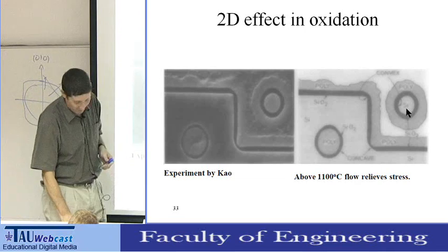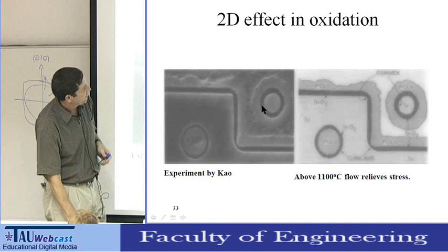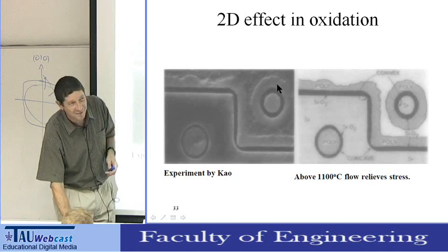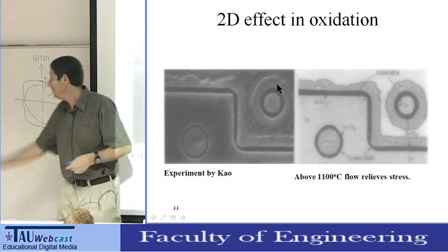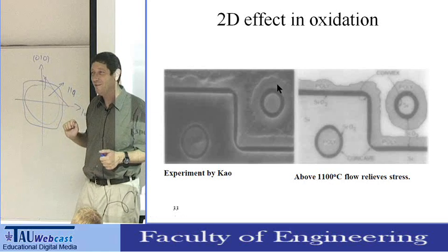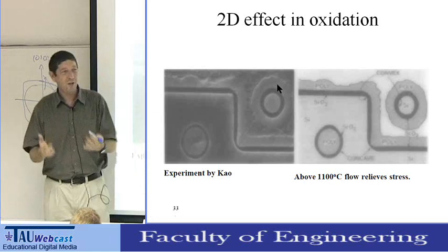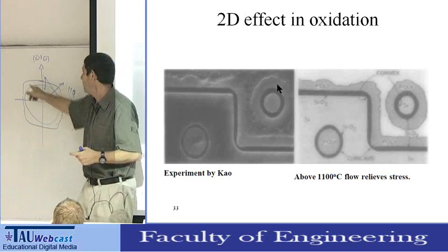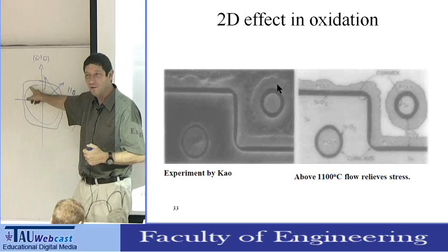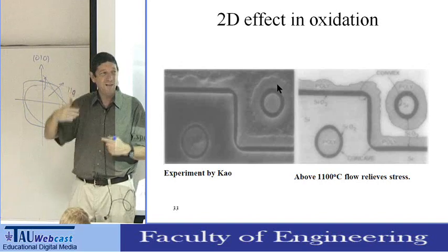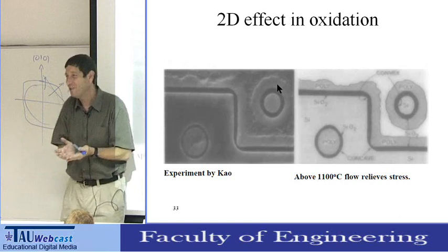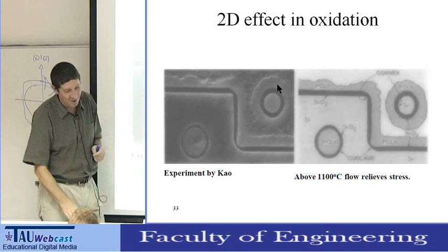And this is why, if you look here in the corner, you don't see this effect much. You see the oxide here is quite round, not what I plotted here. The reason is that if the reaction depended just on the crystalline structure, it would go faster on the sides. But because it grows faster, it has more stress. Then on the sides, the reaction rate goes down, and we get this nice circular shape of the oxide.